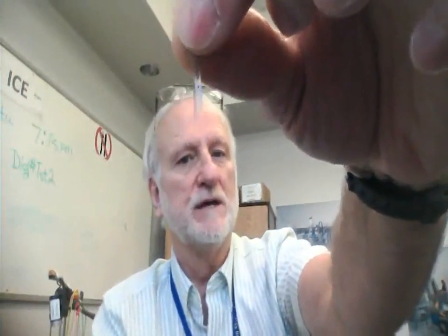There is no set standard on what is assigned to the leads. All the TO92 does is supply this case, this length, the space in between those leads, right? You understand. This could be an integrated circuit. It could be a voltage regulator. A fixed voltage regulator requires 3 leads. It requires an unregulated in, a regulated out, and a common, right? You understand that?